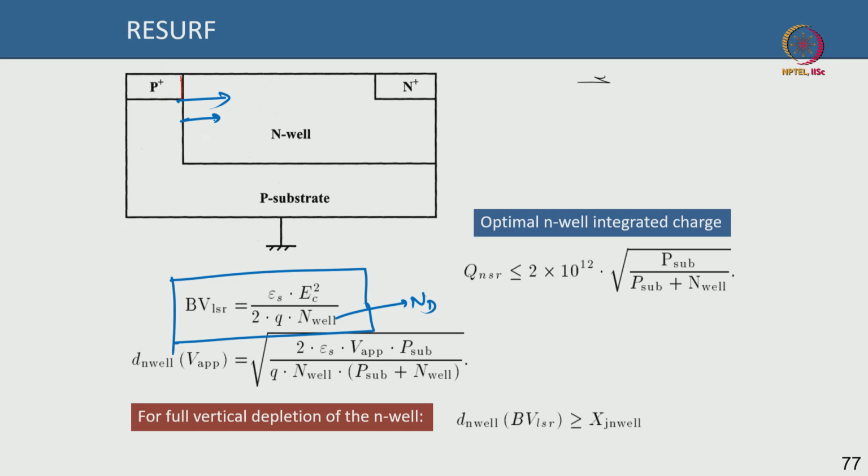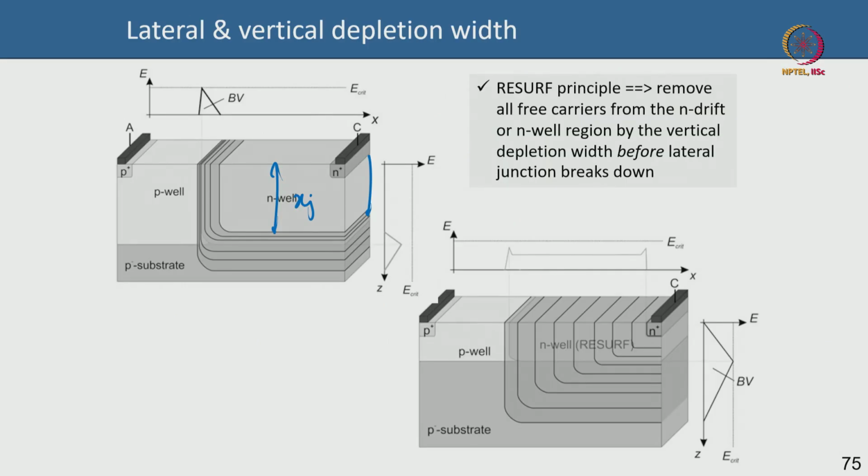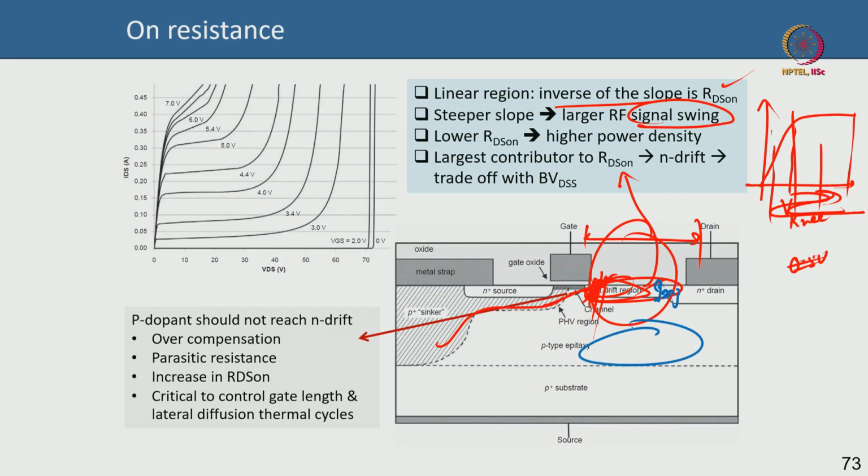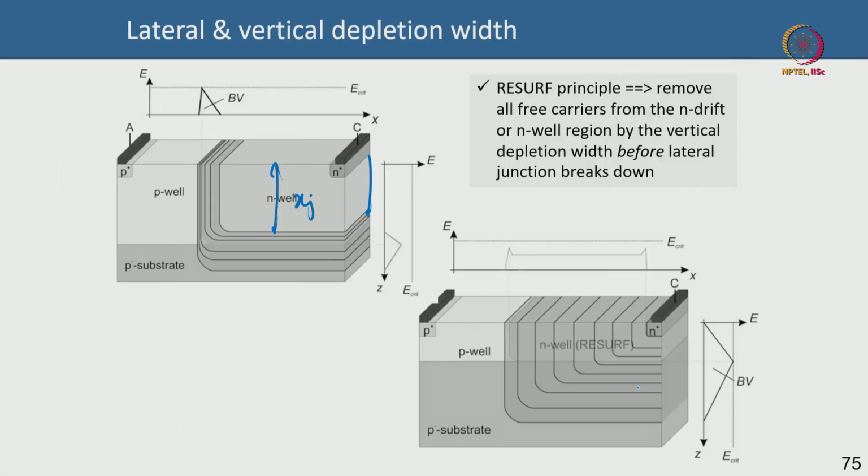Now in the vertical direction, the depletion on this side is this expression under the square root. It is a classic semiconductor equation, nothing fancy. P sub is your doping Na here, assuming this substrate is not the P plus substrate, by the way. This is the P plus, the P epi actually. This is the P sub that they are saying, not this.